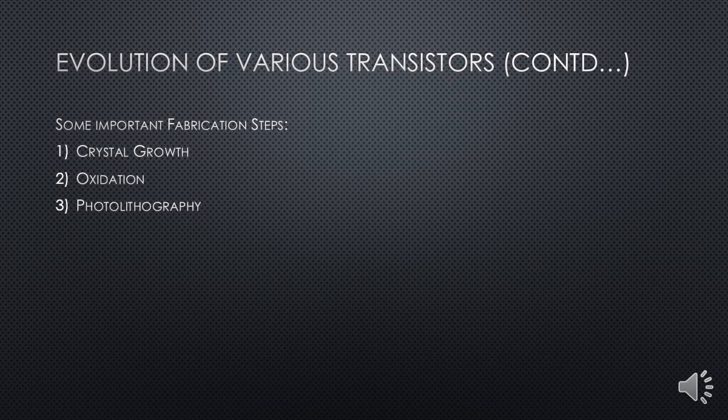So at this point of time, I would like to show how fabrication will happen. Let's suppose we wanted to fabricate one metal shape, which is like this. In order to fabricate this particular metal shape, the first thing we want to have is a mask for this. Let's say we are having a mask like this. As we want to fabricate this in the middle, wherever we want to fabricate such a shape, we will be creating a hole like this. Obviously we'll have the crystal at the bottom like this, and let's assume we have developed the oxide layer on top of that. Let's suppose it is like this.